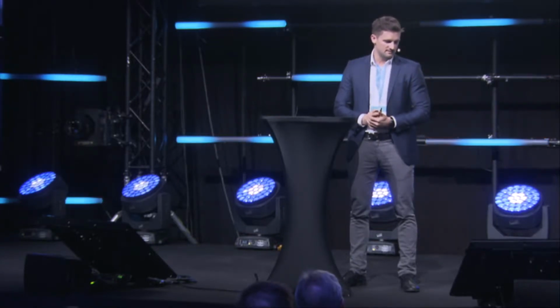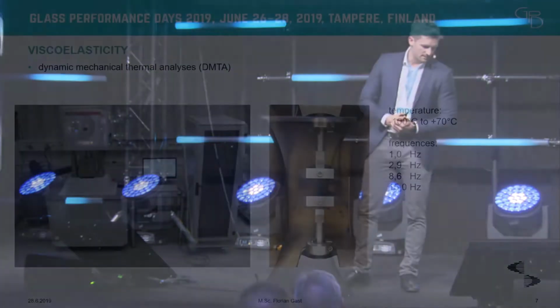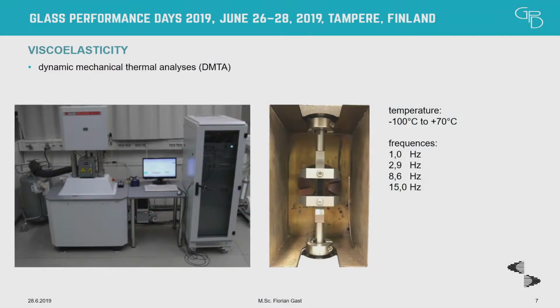This I did with dynamic mechanical thermal analysis, DMTA. You can see it's a huge machine and a really small sample. On the right picture, you can see the sample in the machine. It's only 20 millimeters high, and I cut it out of a bone sample.